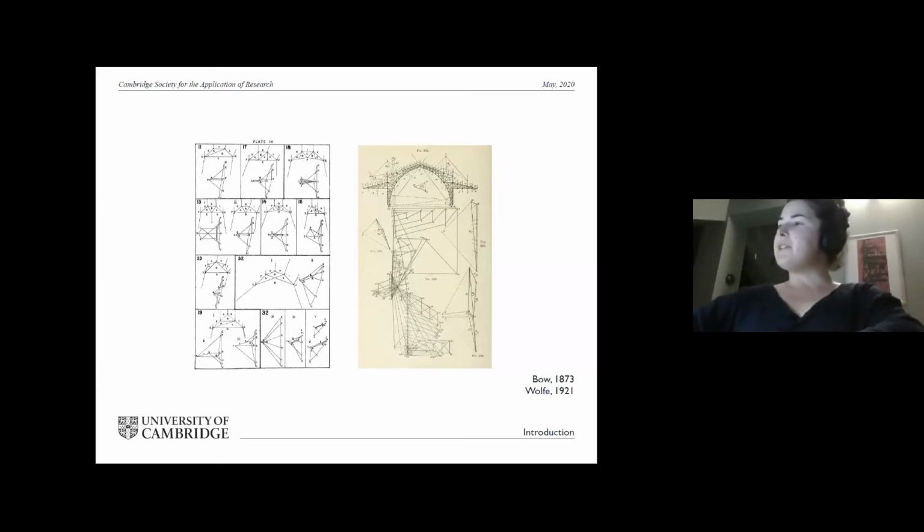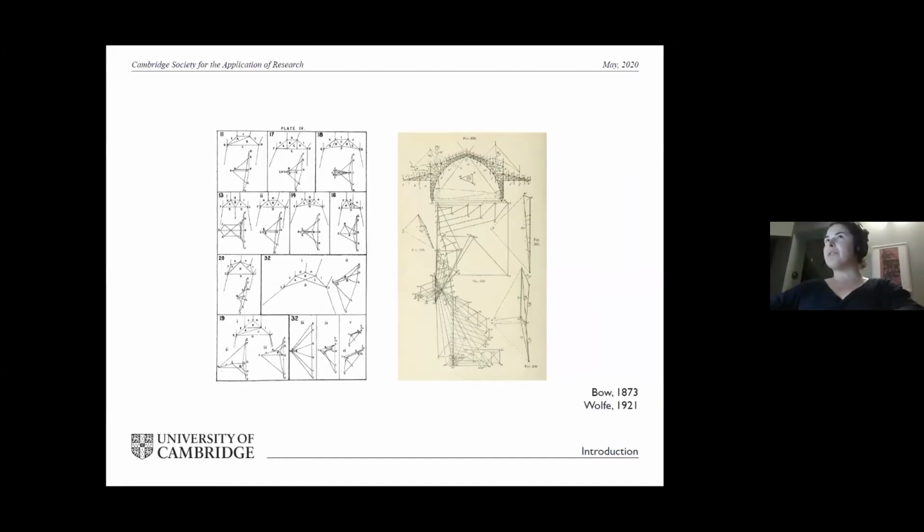And this is very interesting in a number of ways. First of all, you have this very intuitive idea of the forces that go through your structure. Moreover, if you have a force diagram which has all those closed force polygons, you're sure that your structure is in static equilibrium. And more fundamentally, more profoundly, if you see this bidirectional link, it means that you may not start with the form as an input, but you can start with the forces. So you can start designing the forces, and then the form is an output.